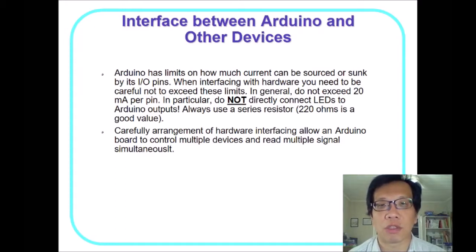Normally when we connect to external devices, we are not only sending out digital or analog input-output signals, we also need to build some simple circuits. For instance, if we want to connect to an LED, we must know how an LED needs to be connected. It needs to be connected to a resistor in order to prevent the current from being too huge and burning the LED. There are many other things we need to pay attention to so that we don't burn